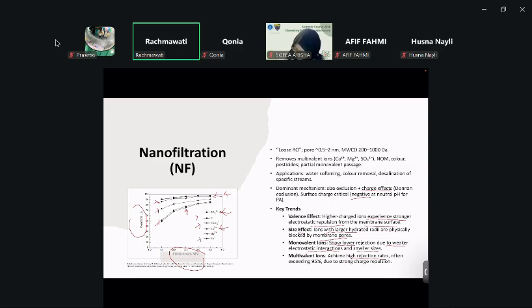So you can see that the ions with larger size, with larger valence, are normally more retained, rejected by the membrane. But a smaller ion with smaller valence might be tricky. Like for example, this one here, and the pressure is very small, so 50% is rejected for Na plus, which means that your drinking water still contains 50% of sodium plus compared to the feed solution.